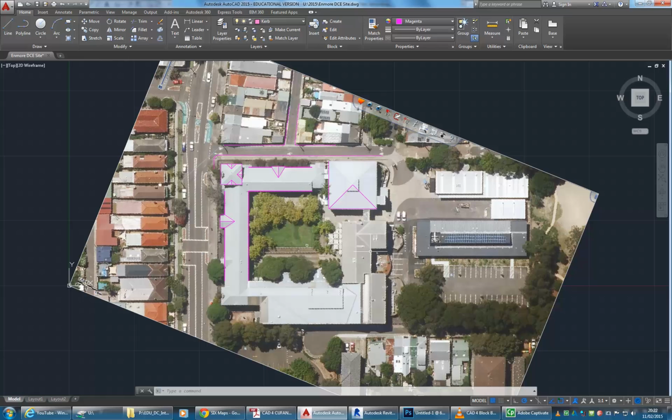And again, for site plans, and definitely for things like locality plans, modelling it all up in 3D is a huge effort, and the site modelling tools in Revit are limited at best. A lot of really experienced Revit people I know who use Revit every day, that's the biggest complaint they have, is the site tools in Revit, because they just are really limited. And it's often not necessary at all, because those things only need to be 2D, so do it in AutoCAD. It's easier and quicker, and probably looks better too.